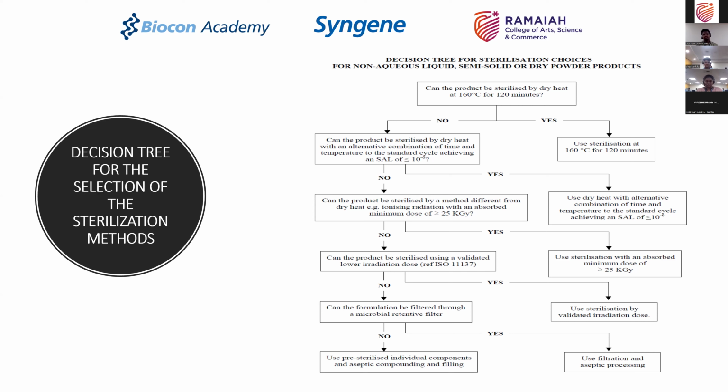That could be a combination of precipitation, so you remove the liquid, or you reverse precipitate it, or you change the phase, or you change the solvent, and as a result the solid gets precipitated out. And then you have to do a filtration to remove the liquid, and then take that solid and dry it out.